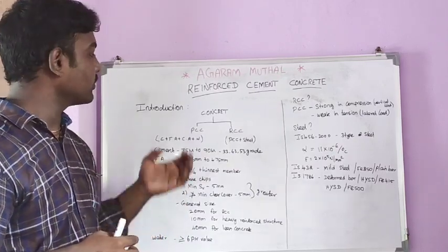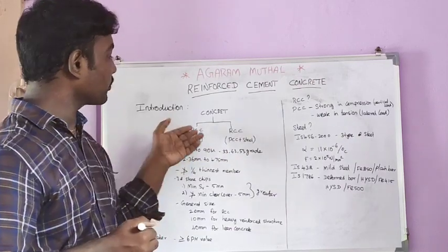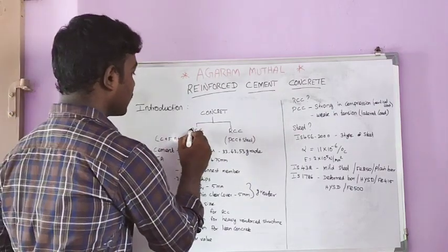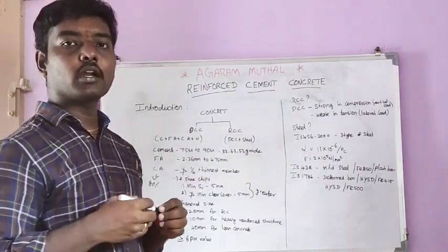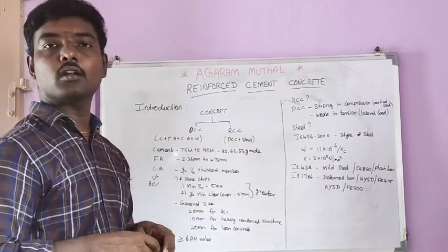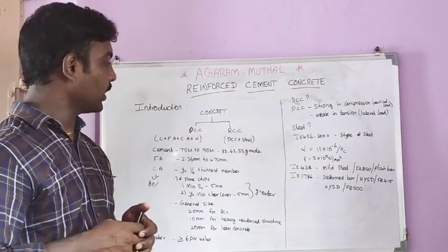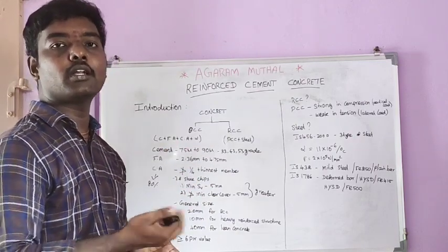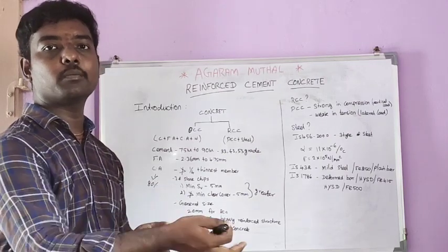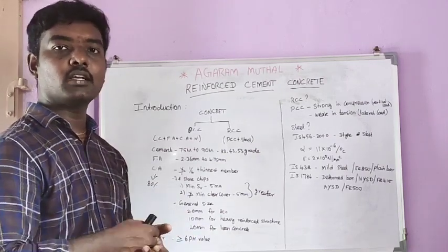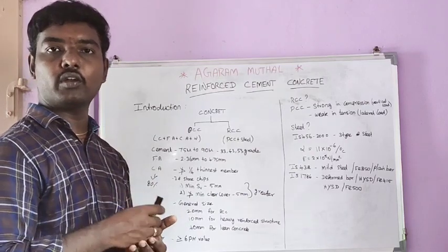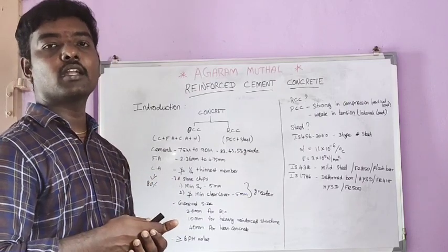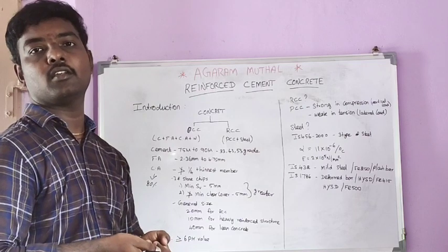These are grades of OPC, ordinary Portland cement. Sorry, earlier I said PCC is porcelain cement concrete, but PCC is plain cement concrete. Nowadays we also get PPC, Portland Pozzolana cement. In it, up to 25 percent fly ash is combined with OPC cement, and that makes it PPC.